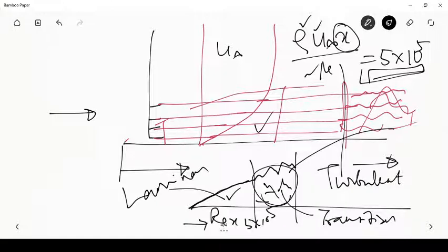Okay, so this is something that is observed on a flat plate boundary layer, and the critical Reynolds number for transition is identified to be 5 into 10 to the power of 5 by various experiments. There are people who also work on mathematical stability of these flows, and using the stability theory and perturbation analysis also, the limits of stability of laminar flows have been determined theoretically. That's also available. So this 5 into 10 to the power of 5 is the number for external flows, whereas 2000 to 2300 is for internal flows through a circular pipe, right? So that is the expression that we have.